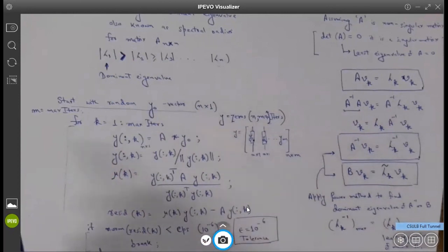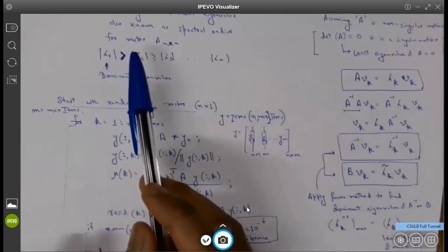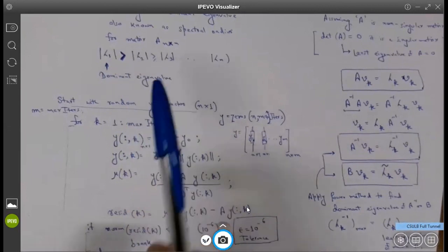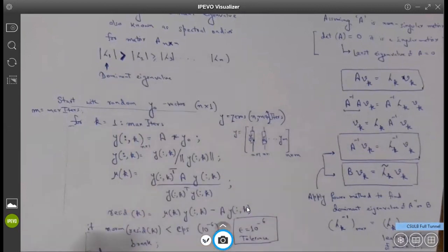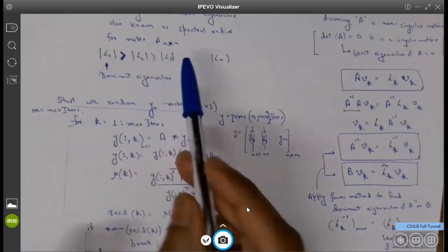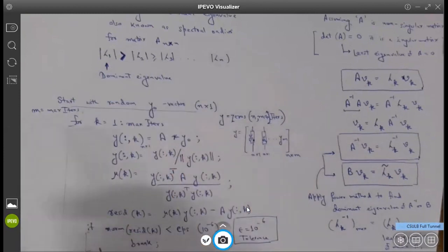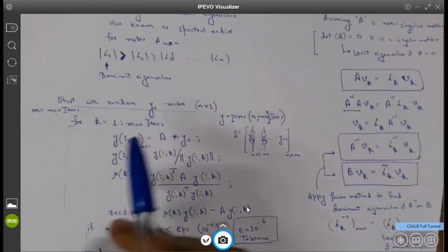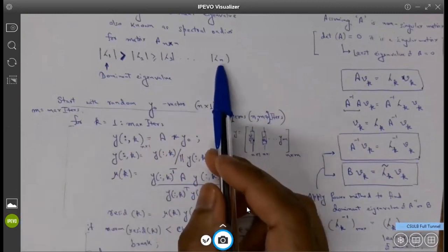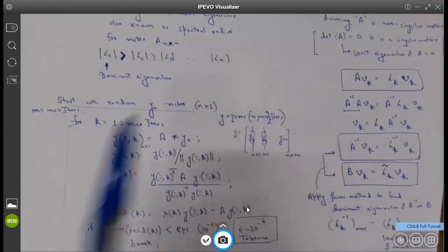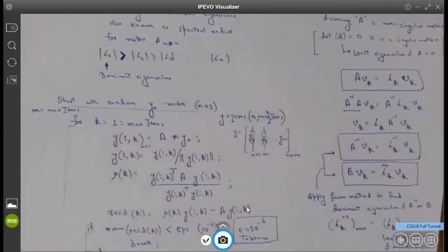If you think about the dynamics of a system like a beam which has vibration, like a bending mode or axial mode, those modes correspond to these eigenvalues, and the eigenvectors correspond to the mode shape. So generally we are only concerned about the first 5 or at most the first 10 eigenmodes, not more than that. If your question is what is the significance of this, at this point I'm not sure what the physical meaning of that eigenvalue is. It is just an eigenvalue of the system, but it is the least eigenvalue of the system.